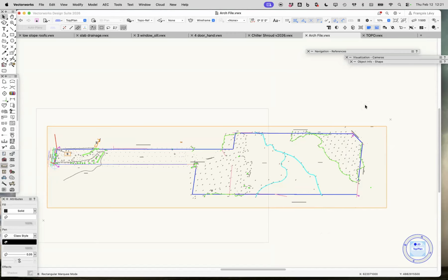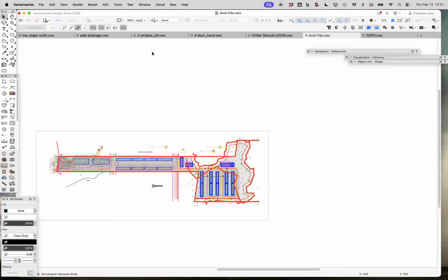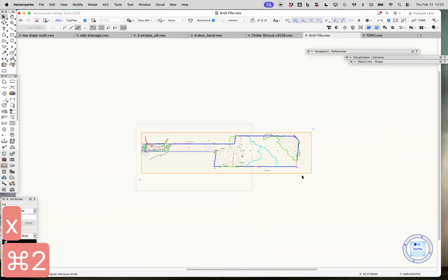So if I wanted, for example, on my architectural sheet set, a site plan that has topos and nothing else, but then another site plan where I want to show utilities and building infrastructure, because those require different class visibilities, what I would need to do over here on the sheet layer is have multiple instances of this viewport, each one with its own class setting.